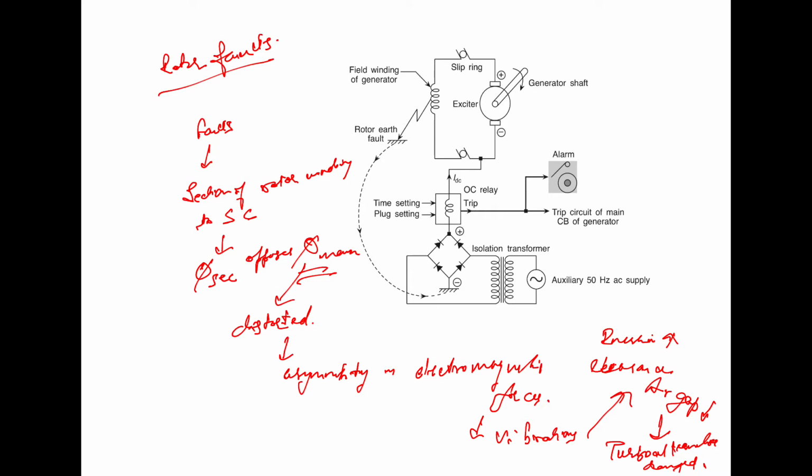Instances have been reported where, during rotor faults, because of severe mechanical stresses, structural damages are caused. So from this we see that the very first fault on the field winding must be detected and the set tripped in a controlled manner. Now, the figure shows an arrangement for the rotor earth fault detection and protection as shown here.